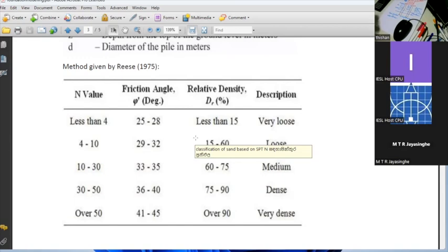Through the piers, the braking load can be transferred onto the piles. So if you would like to know how the piles are going to react, then modeling the pile alone is not enough. You have to model the pile and you have to model the soil as well. To model the soil, you need to know the horizontal subgrade reaction, and depending on the type of soil, you can find it.